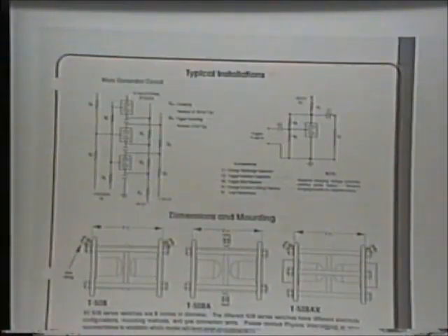The deal here is that spark gap that we just saw. And when you take this spark gap and you put it with capacitors, just a few stages, you're into hundreds of thousands of volts with thousands of amps. The thing's called a Marx generator, and they're used in plasma studies by universities and other sorts of organizations.